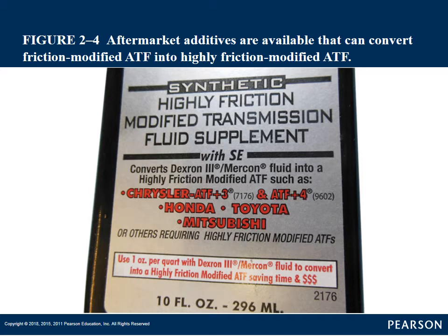A lot of times your Dextron 3 or Mercon is your base, because that was used in most vehicles. Ford, GM, Chrysler, earlier Toyotas, all used some form of Dextron earlier in their transmissions.